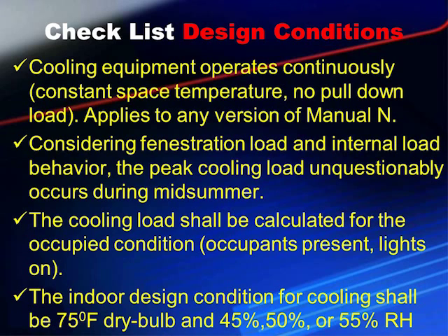Considering fenestration load and internal load behavior, the peak load unquestionably occurs during midsummer. The cooling load shall be calculated for the occupied condition. Occupants present, lights on. The indoor design condition for the cooling load shall be 75 degrees Fahrenheit dry bulb and 45, 50, or 55% relative humidity.